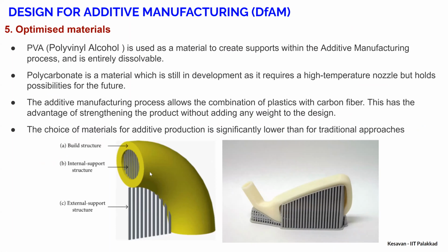Because it is overhanging, see, it is overhanging. The moment you construct this layer by layer, when it comes to this higher or top location, the part will collapse. So to avoid that, to minimize that, you need to anchor them. So basically what you are doing is some scaffolding, right? Or you are supporting that. So that's the reason it's called supports, right? So you need to anchor from the base plate. That's called primary support. If you are anchoring within the structure, it's called secondary support.